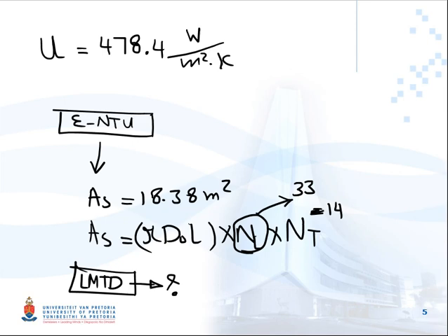But do all the temperatures need to be given as values? No, sometimes by having just three values you can apply the energy balance and find the fourth, missing temperature. But sometimes even by applying the energy balance you cannot find all those temperatures.